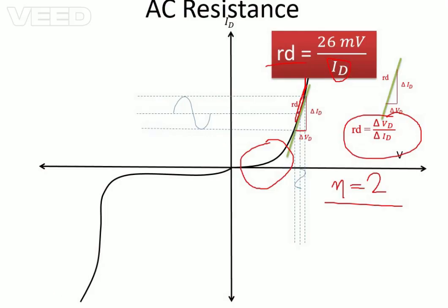And at this point, I will also tell you that in many competitive exams, this was asked: for a characteristics curve, for the lower region of the graph, the dynamic resistance or AC resistance, option 1, it gets decreased, it gets increased, it does not vary. So you have to tick 'it gets increased'. The dynamic resistance always increases in this part of the region where we have gradual increment, where we have a big slope of the curve. It's not the steeper region.